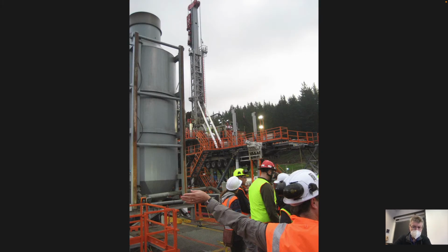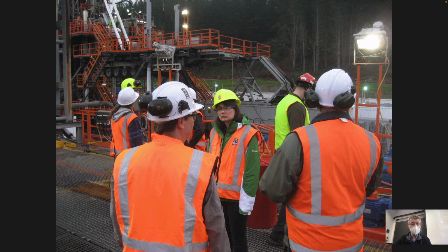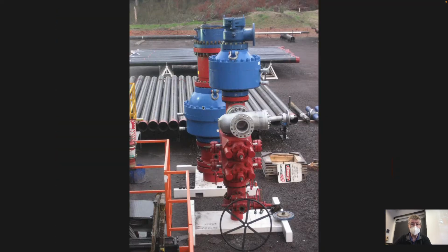And so this is the drill rig, comes in on a multi-wheel trailer, lifted off the ground. The mast is raised, and then all the other accoutrements that go with it. Blowout preventer. So drilling through here into something that's anchored to the ground, with the idea that the hot geothermal fluids that can flash to steam and basically explode are contained by the pressure that's applied here. I guess with these stacks you can also shear off the drill pipe.